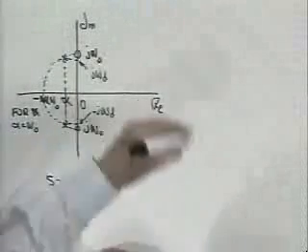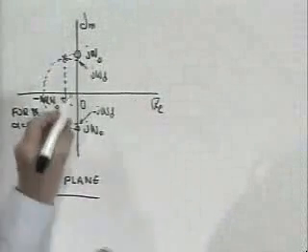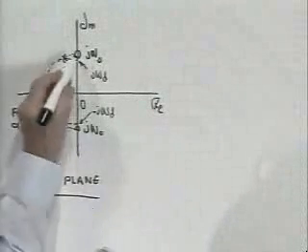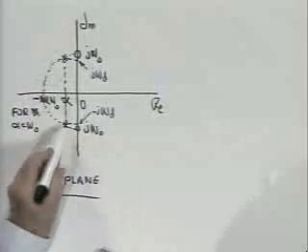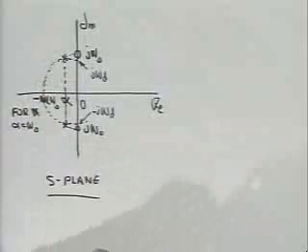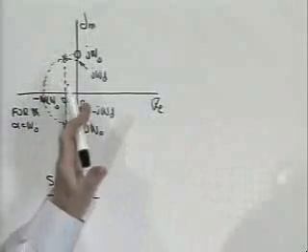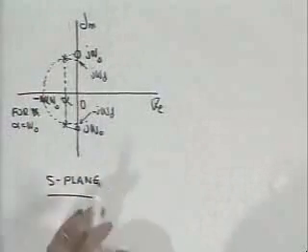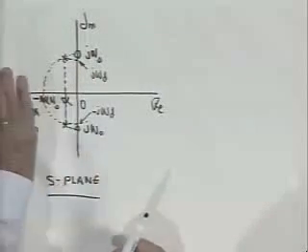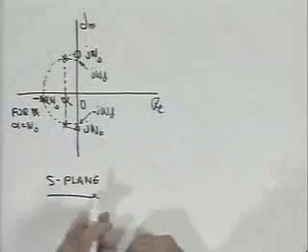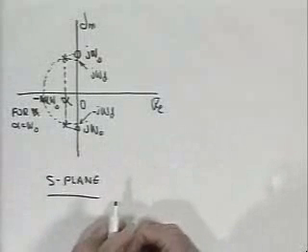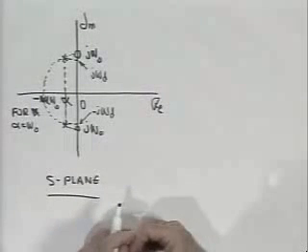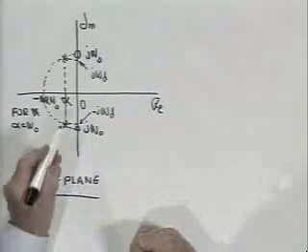Here, the sheet, of course, is nailed down all around the edge, nailed down at these two zeros, and pushed up infinitely high at these two poles. If you imagine walking up this imaginary axis and looking at a cross-section of this stretched sheet, you can get a sense of how the magnitude of the transfer function behaves.